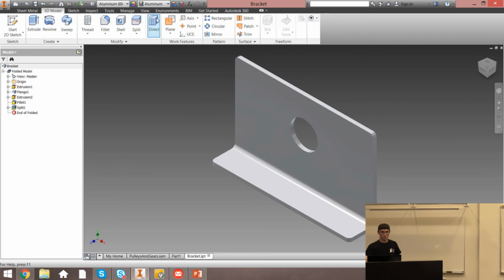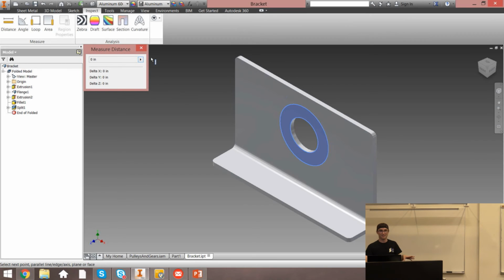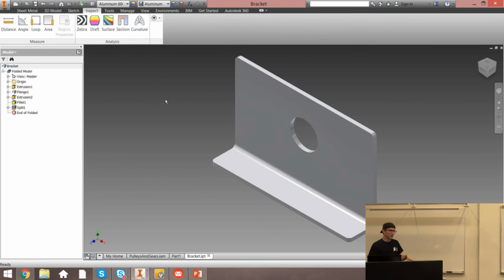Even though, if you look at the part thickness, it's exactly the same. There is a neat trick where you can come in and just extrude a really, really small portion of it out, but it looks really funky and you have to undo it later. So I really recommend using the split tool. It makes everything easier and it doesn't really take away from anything.